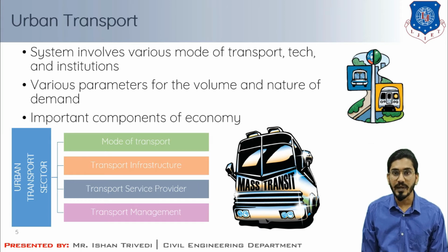Detailed data on current travel pattern and traffic volumes are also needed for developing the travel forecasting and prediction models. This will be discussed in a later session. So these are the models which are useful for forecasting any travel demand. The prediction of future travel demand is an essential task of the long-range transportation planning process for determining the strategies accommodating the future needs. These strategies may include land use policies, pricing programs, and expansion of transportation supplies in the highways and transit services. So this is transportation planning in this context.